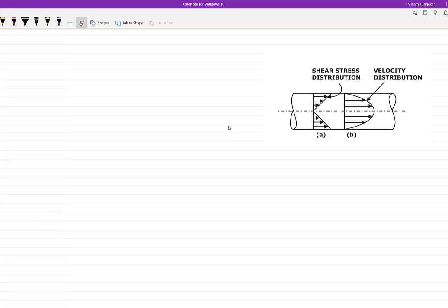It is a laminar flow. The length of pipe is 3 meters and the diameter will be 2 centimeters. Again, in order to get this profile, we will be using the basic equation, which we find in every fluid mechanics textbook, which will be mu times change in velocity with change in y. I could say mu times change in velocity with radial direction. In our case it will be this, because our radius will be in the y direction.